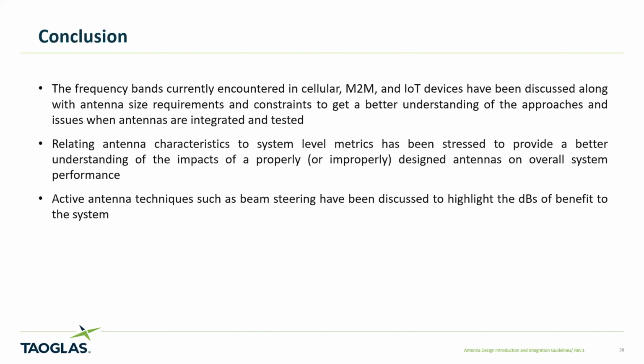As it turned out, we were told no, most of the time for that access point sitting in your home, it's doing adaptive beam steering, because they were getting better connectivity, higher SINR or higher SNR, by forming in the digital domain a 4-element array instead of trying to drive it as a MIMO. Very close to the device, it might be in MIMO, but typically we were told 90% of the time it's in adaptive beamforming mode.